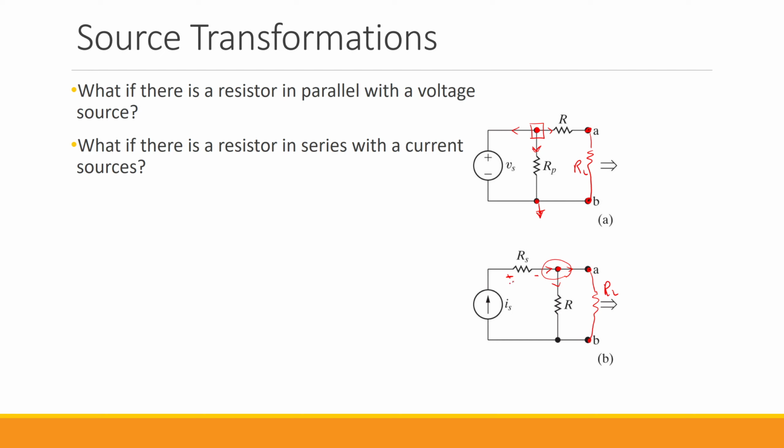For example, because this current goes through RS, we have a voltage across this RS, so instead of using Vs, I can write the voltage across this RS equals RS multiplied by Is. And if you have in your circuit any KVL written, you can easily see that the equation for KVL would be different, whether you have this RS or you don't have it. But in terms of the current that RL is getting, having RS or not having RS are both producing the exact same result.